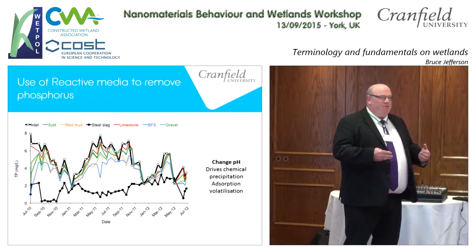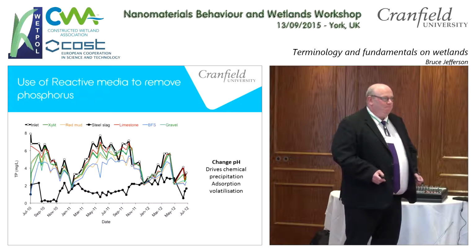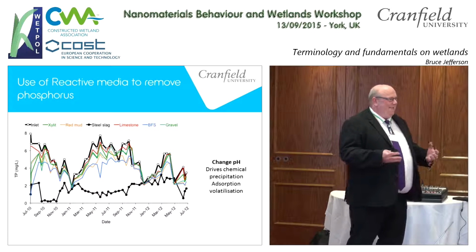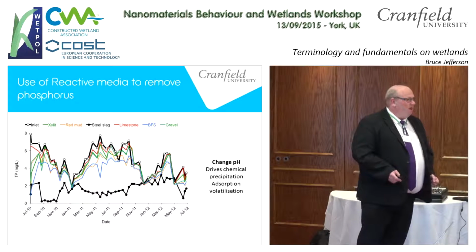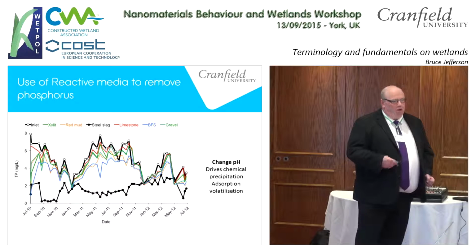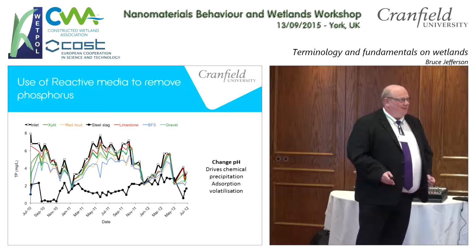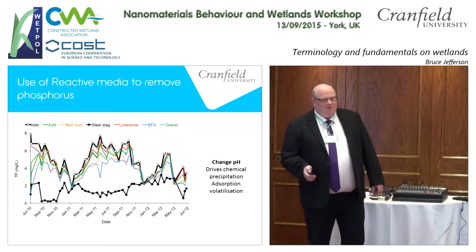Unsurprisingly, these beds are very good at removing metals, because they precipitate them all out into the structures of the calcium carbonate. It makes the calcium carbonate worth nothing, but it is actually a good pathway for metal removal. It's not such a good pathway for discharge at pH 11, but that's a slightly different challenge.